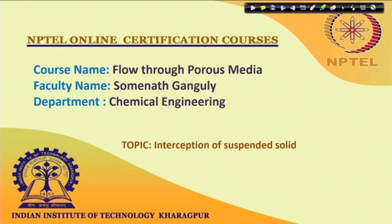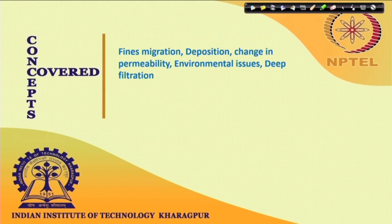I welcome you to this lecture of flow through porous media. We have been discussing the interception of suspended solids. At the end of the last lecture, we started discussing the reason why these fines get migrated in a porous medium. That means a part of the porous medium itself, which was attached to the wall, is now getting dislodged from the inner wall and traveling downstream, and essentially that is being intercepted at the downstream. So, we have been talking about fines migration in this lecture.